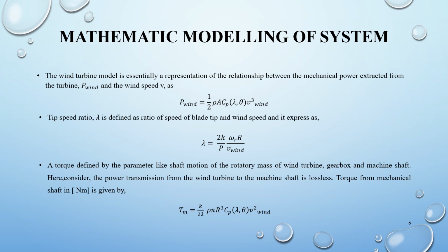Wind turbines with variable speed are built to operate at their highest aerodynamic efficiency in the various kinds of wind conditions. It is now feasible to continuously adjust the rotational speed of the wind turbine to the wind speed, that is, variable speed operation. In this manner, the tip-speed ratio lambda is maintained constant at the maximum power coefficient, which is a predetermined value.